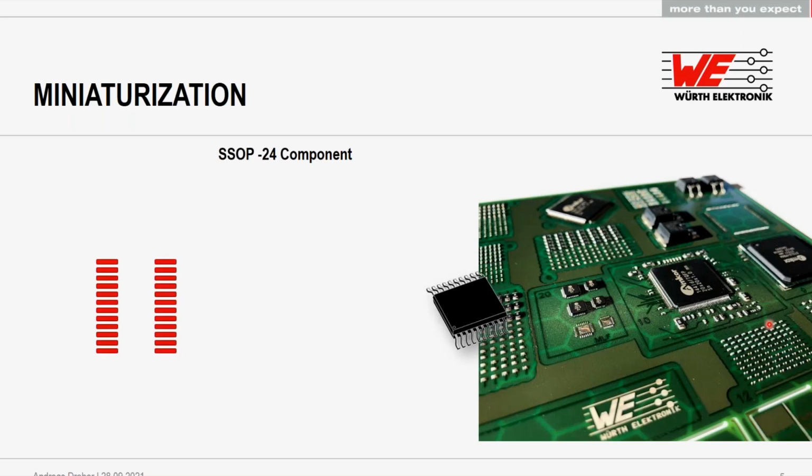Let's choose a simple SSOP component with 24 connectors. In this example, we have a pitch of 0.65 millimeters. The pitch defines the distance between the middle of one pad to the middle of the next pad.